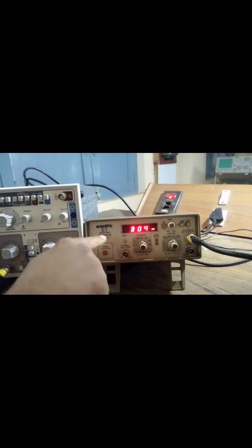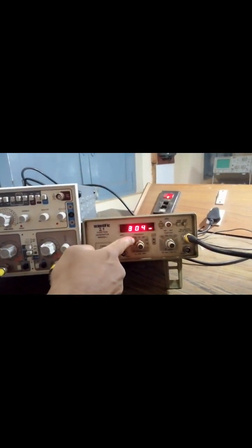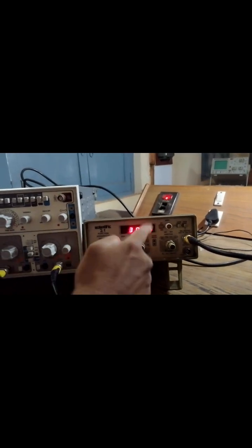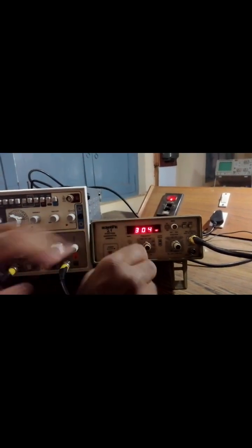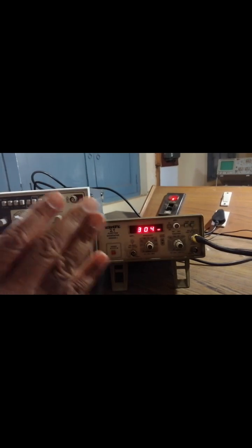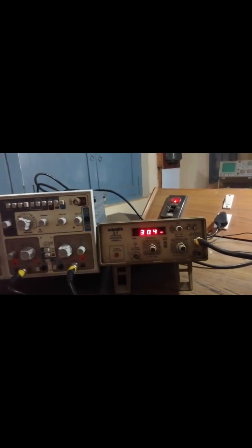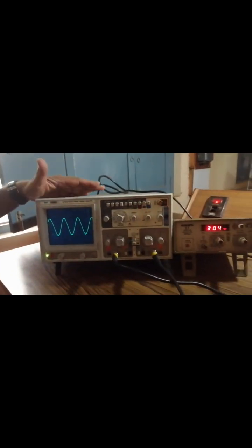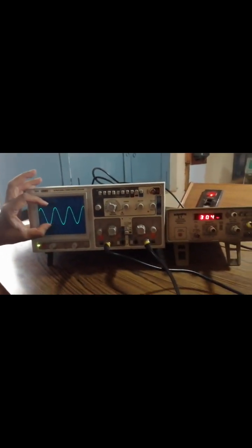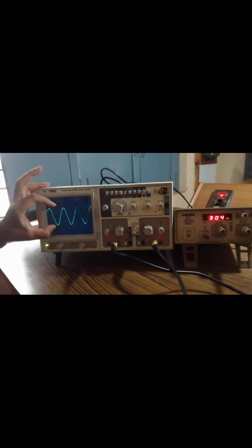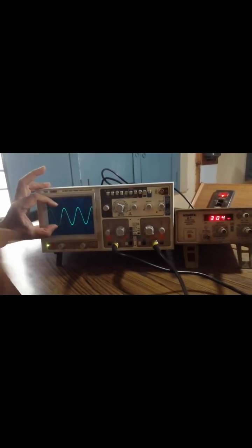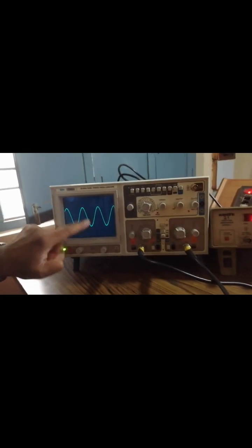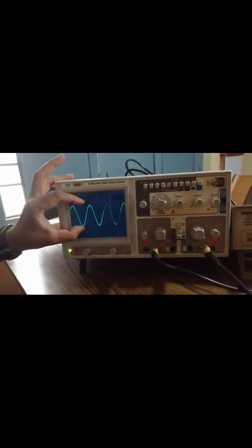According to the data, the frequency given is 300 hertz. So for the signal generator, we have chosen a sine wave as an input with a frequency of 300 hertz. First, before starting your experiment, make sure that you are getting a proper sine wave by feeding your signal generator, directly connecting it to the CRO, and set your Vin peak-to-peak value to a certain value. I have taken in this case 4 volts. It is exactly from positive peak to negative peak, 4 volts.